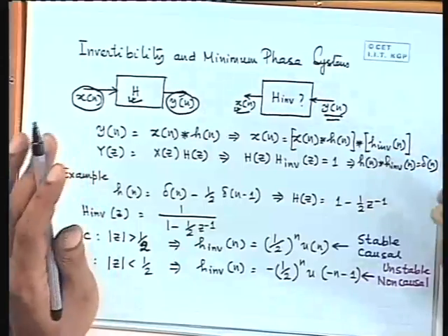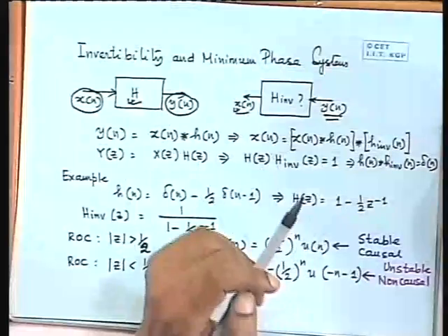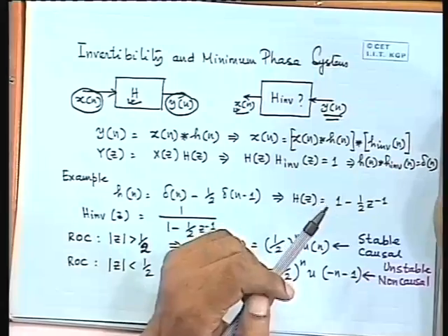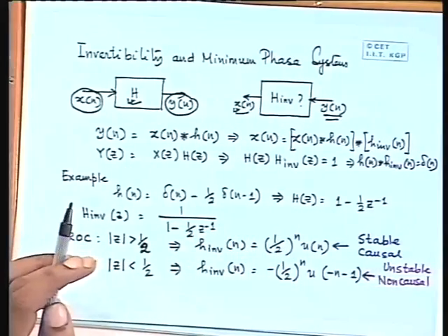This is a standard geophysical signal processing requirement. They will sometimes call it deconvolution. So y[n] is obtained from x[n] by convolution, and you want to deconvolve y[n] to get back x[n]. So the question is, when is it possible? It is not always uniquely possible unless you make assumptions about stability and causality.